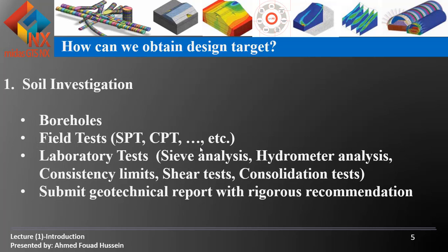Sieve analysis. We need a sieve analysis so we can divide the soil particles by size, and have a judgment about the size of the sample. Hydrometer analysis is another particle-size technique, but sieve analysis with sieves is for large soil.